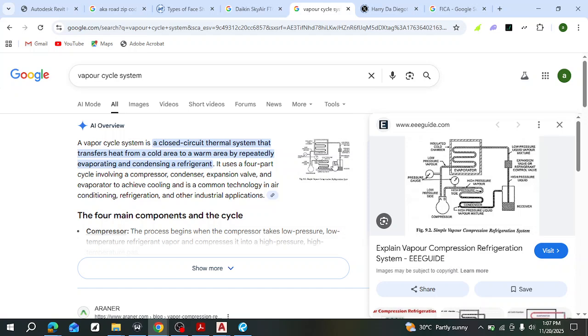The content of the coil is usually liquid at that point. When the refrigerant in that coil extracts that heat, it boils, changes its phase to gaseous phase, just like when water boils.